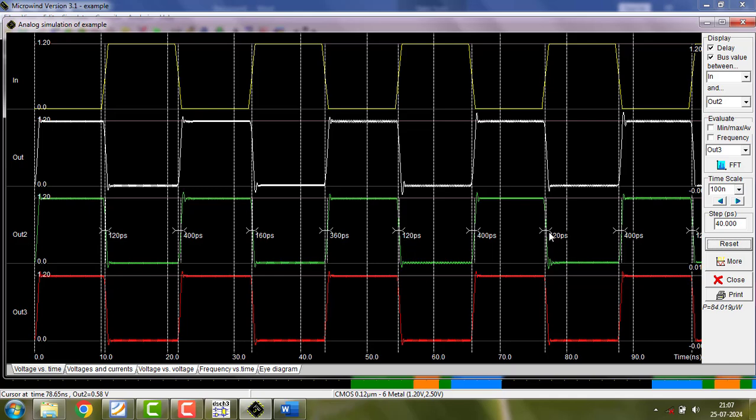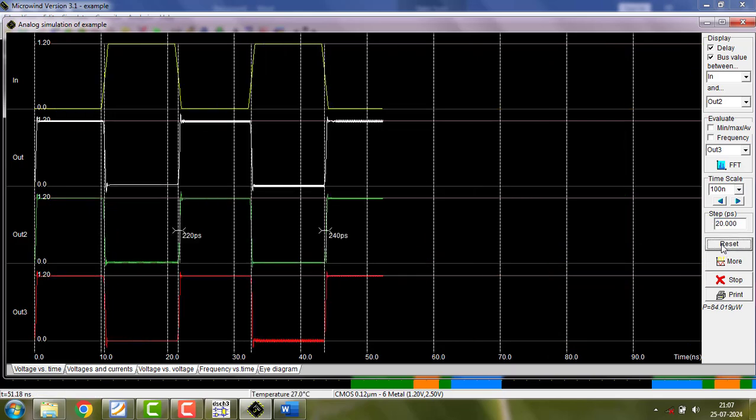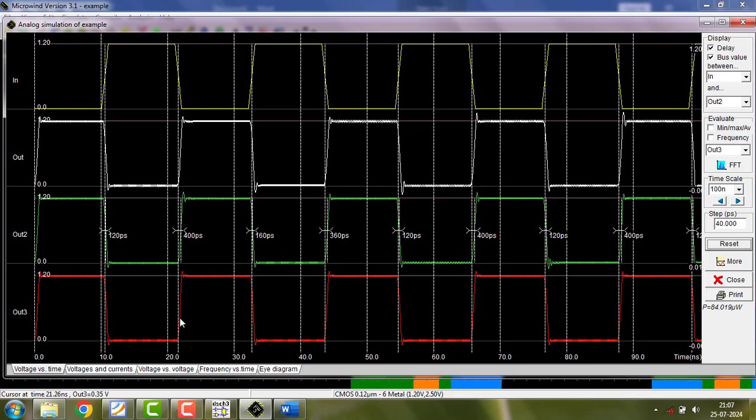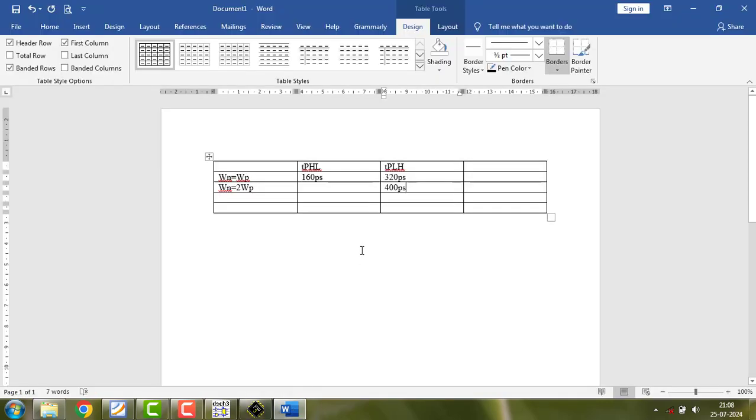About 120 picosecond. Okay, 120 is repeated, only 160 somewhere here, because suppose if I try to do 20, you may get better, but I don't want to take this and confuse you. So here it's showing only rise, so we don't want this, it's a primitive software. I just wanted to take everything in consideration. So 120 is common, many times it is repeated. You can see 120, 120, 120. Somewhere we got 160. We are taking the values which are common, 120 picoseconds.